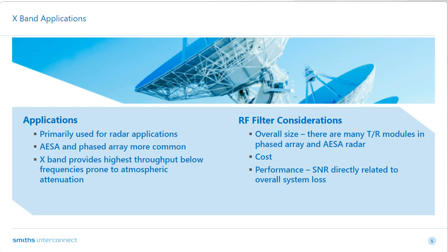support these radar systems. The RF filters are needed in the up and down converters in these systems, as well as other areas. They are needed to filter out harmonics and subharmonics generated during the frequency conversions for the systems to have sufficient signal-to-noise ratio. The overall performance of the system is directly impacted by the signal conditioning of each of the channels.